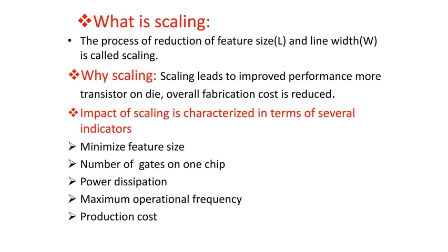So the purpose of scaling is to minimize the feature size, number of gates to be increased on one chip, power dissipation to be reduced, operational frequency to be maximized, and moreover the production cost to be improved. So these are in short why we go for scaling.